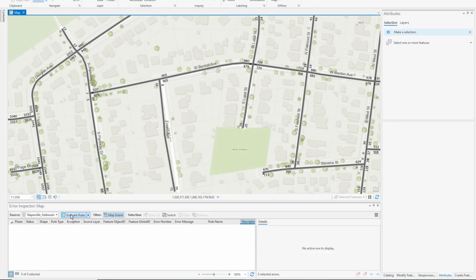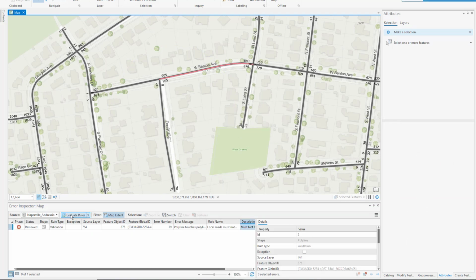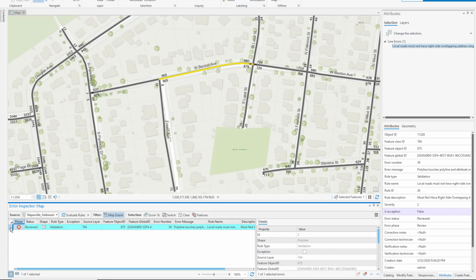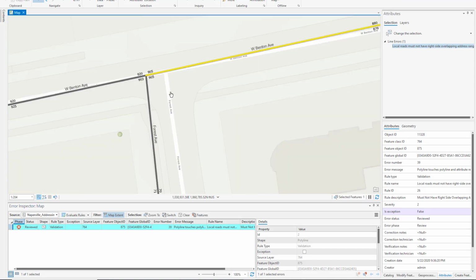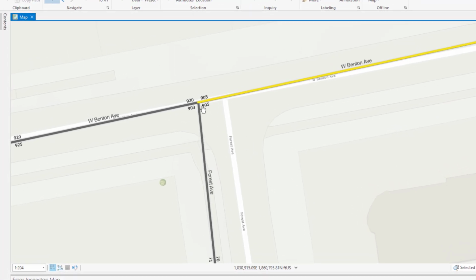The feature on feature check finds features that have user-defined spatial relationships with other features. At this release, this check is enhanced to also evaluate the feature's attributes. In this example, touching road centerline features are flagged as an error if they contain overlapping right-side address values.